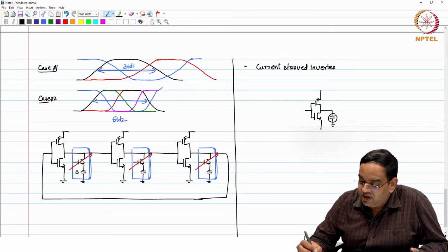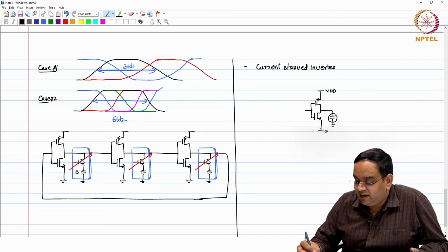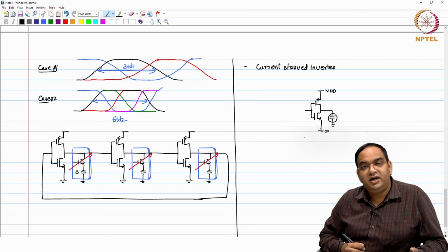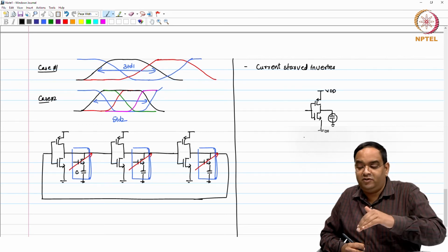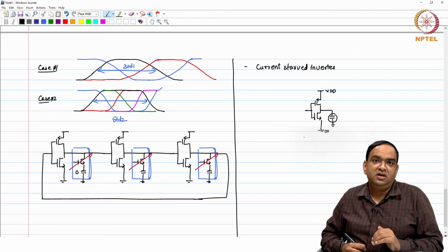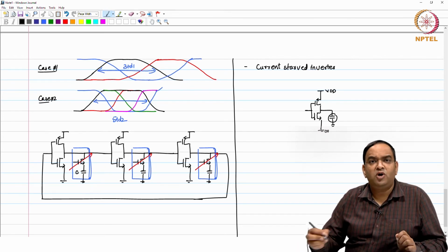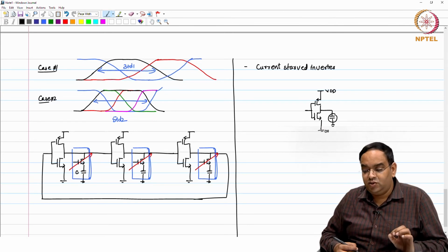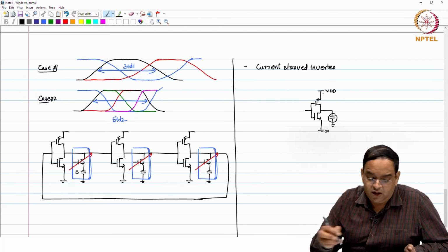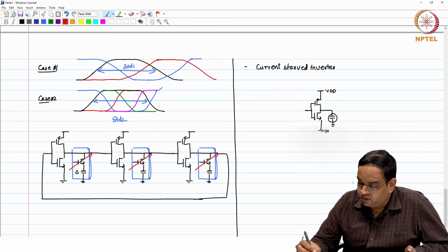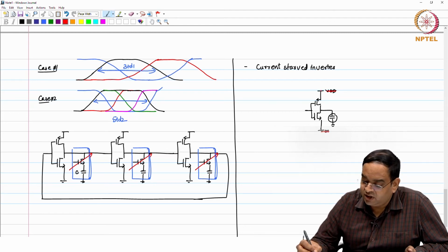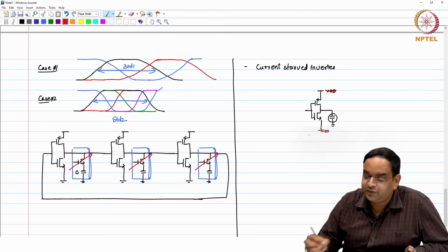When we were connecting this node to VDD and ground, whatever current is required from VDD was used to charge this capacitor, and the NMOS was able to operate with full gate to source voltage to discharge the capacitor. Now, we say okay, this is no more VDD, this is no more 0. I am going to constrain both these nodes.